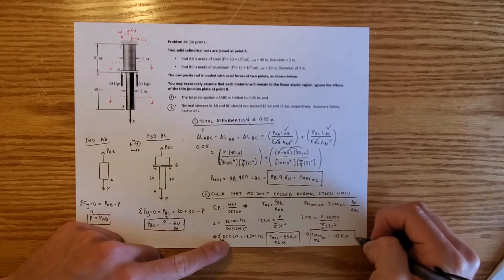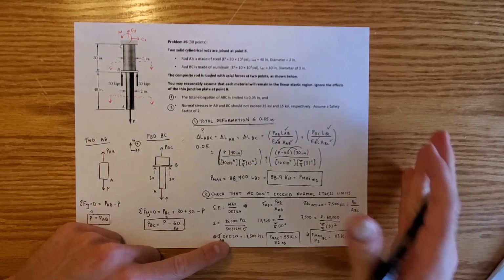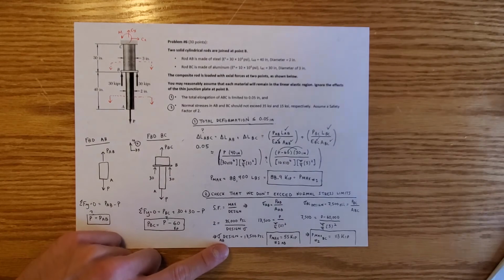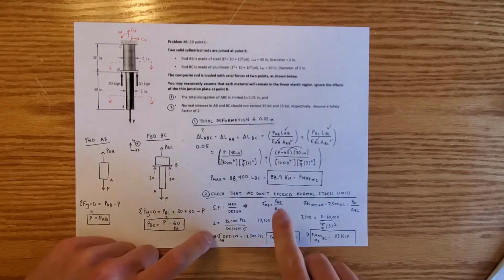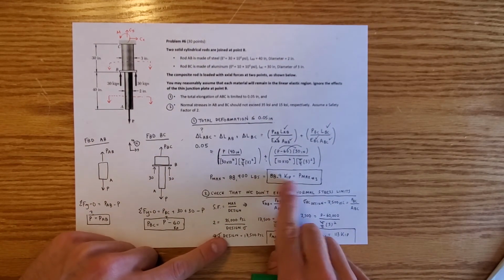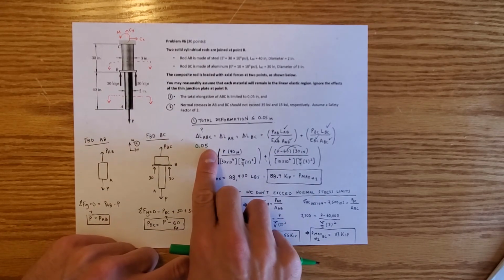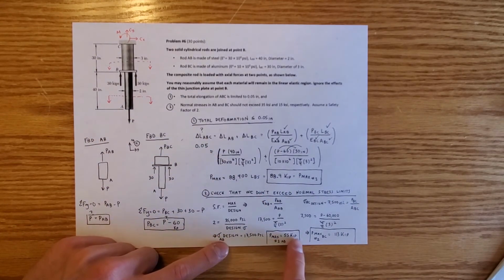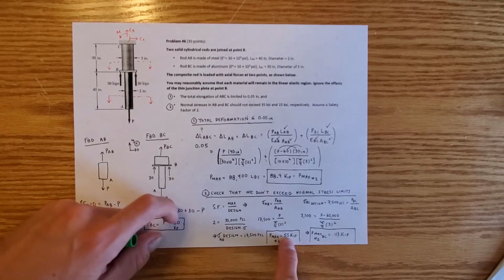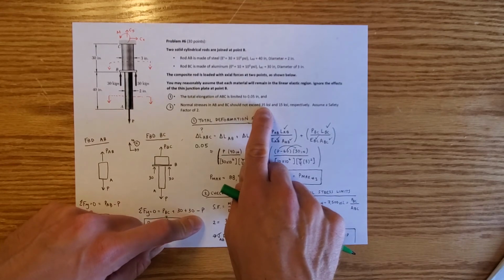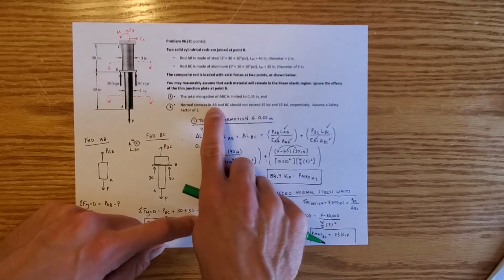Now our last and final question that we have to answer for this whole problem is, which of these 3 forces is the maximum P that we can provide? Well, if we apply more than 88.9 kips, then our rod would deform more than 0.05 inches. If we applied 55 kips or more, then we would exceed the limit in this particular case, which is we would exceed the normal stress that's allowed in AB.